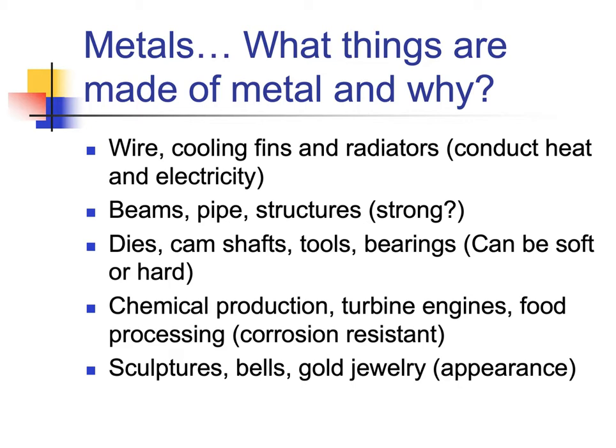But what's interesting is you can actually make a die out of the same steel that you're cutting. So you could have one of them in the softened condition and one of them in the hardened condition, and then that die will actually cut whatever that piece is.